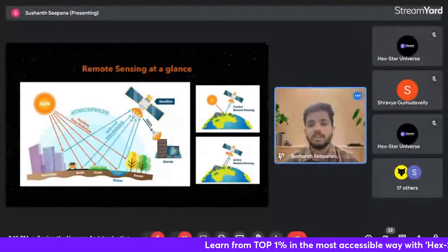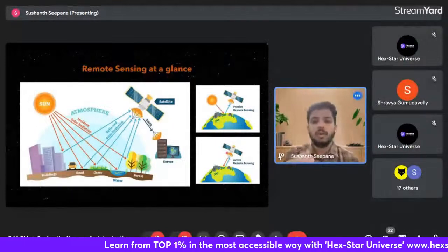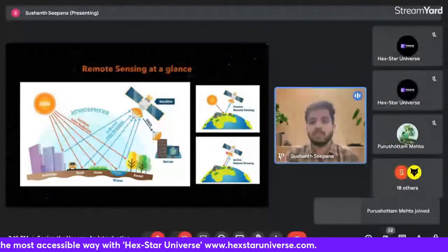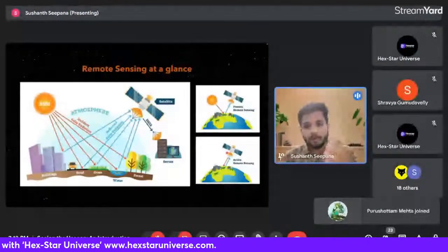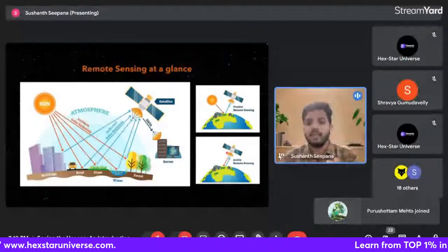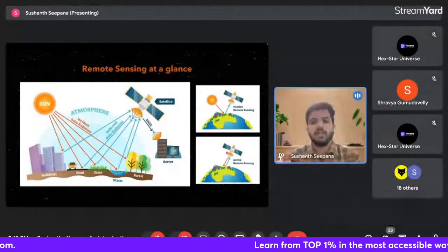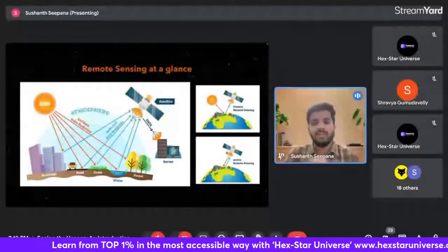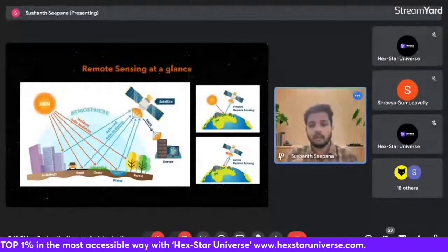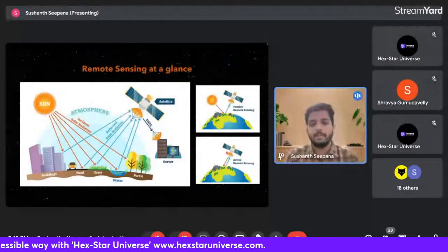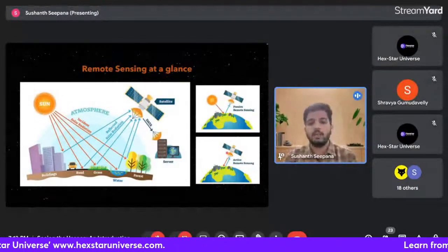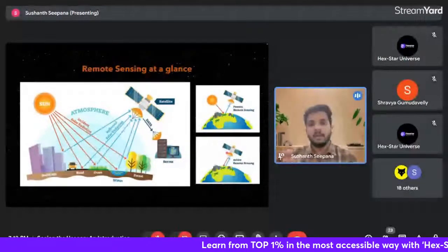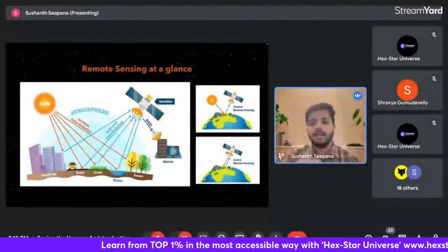Passive remote sensing, you do not employ your own electromagnetic energy source. It's that the energy coming from sun is being used passively. You can see it in a different way, like you're moving ahead with a torch. You're moving on a road and you just have sunlight, but when it's night you utilize a torch. So here you're having your own energy source. In a similar way, some kinds of satellites employ their own energy source, they send the radiation, they capture back the reflected radiation. These are active remote sensing satellites.